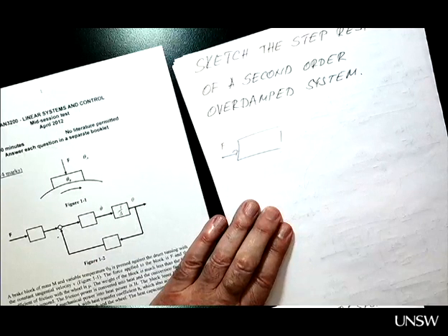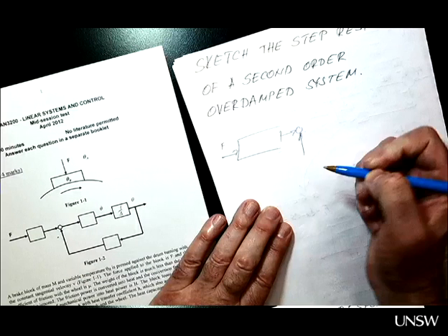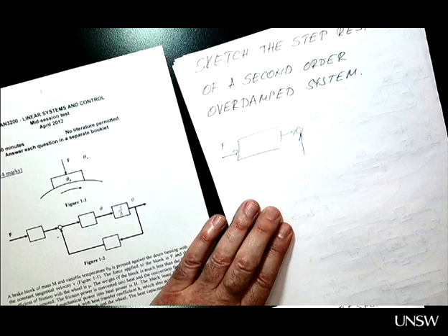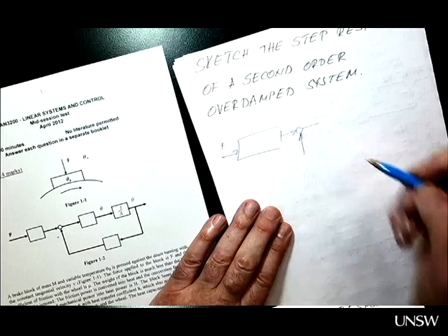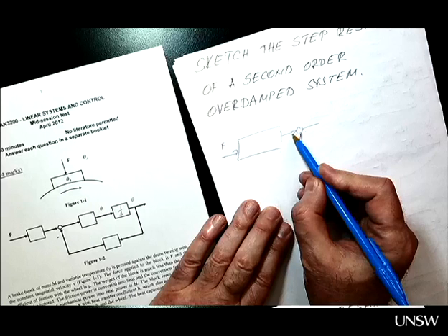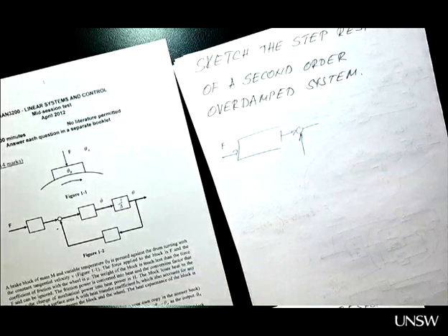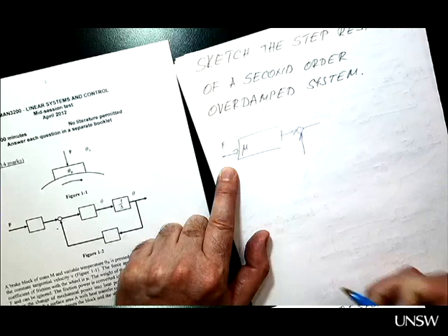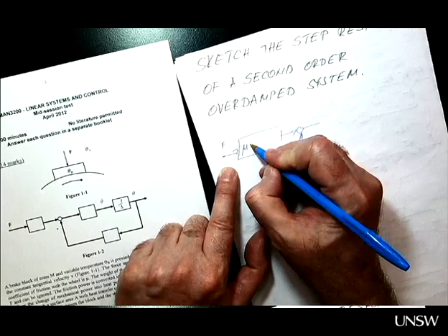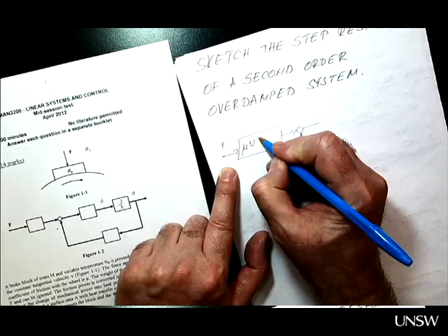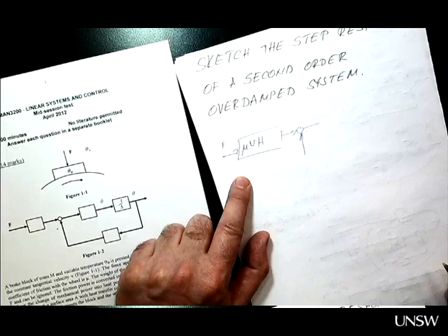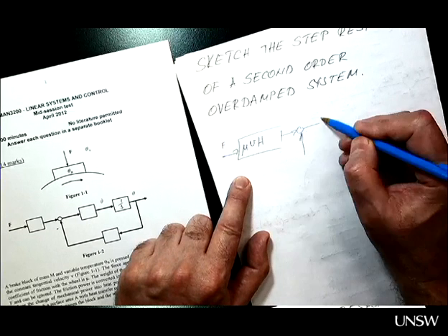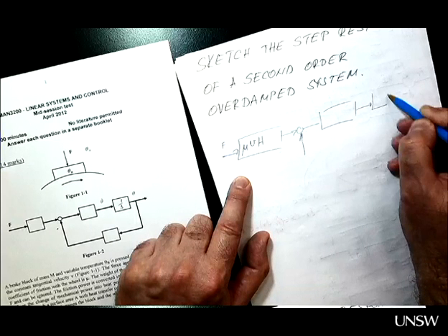Here you have 2 different rates of heat, one subtracted from another, to give us the rate of change of internal heat. So this is what generates heat, what brings the heat into the block. And that is mechanical power, so force times velocity. Force is already here, but the force that generates heat is friction force. So it's mu F times velocity and times the conversion factor, because this is heat. This is temperature.